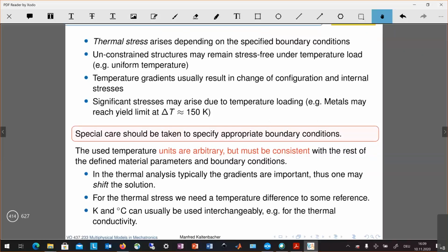And especially important there is to compute in a post-processing the mechanical stresses and look how large they are and if they are below some value, in order that you still be within the elastic behavior and not go perhaps towards a plastic behavior, which at the end perhaps will break your electronic device.